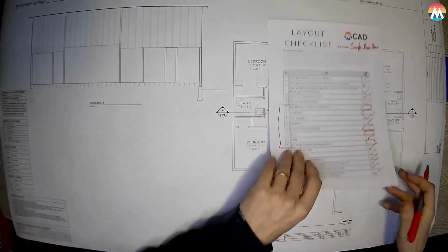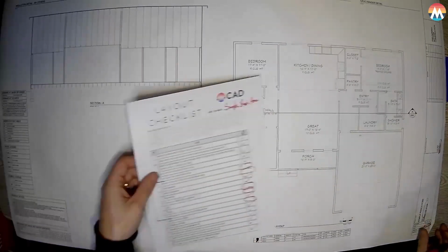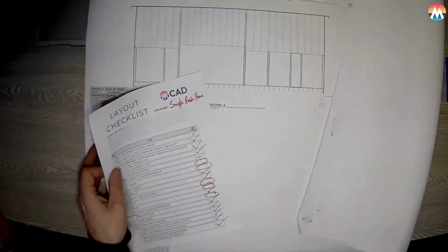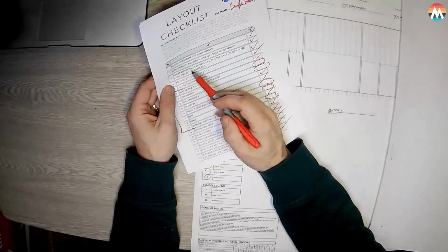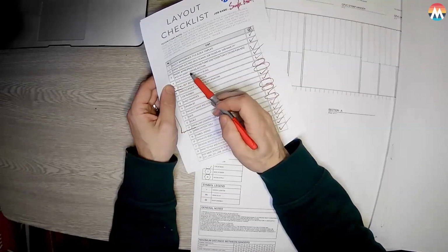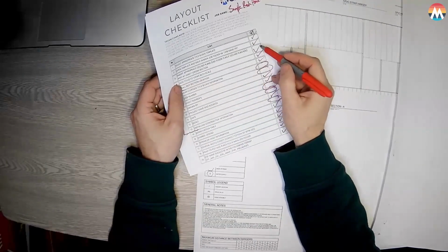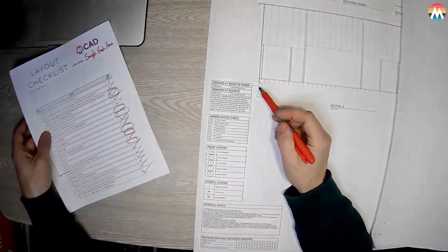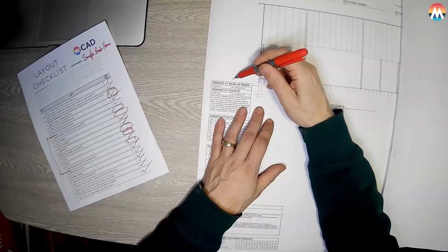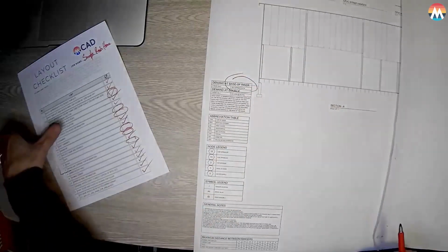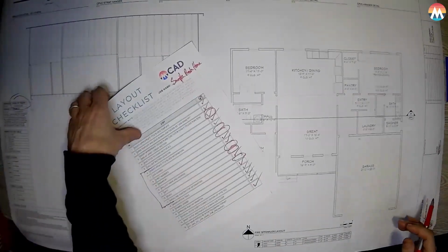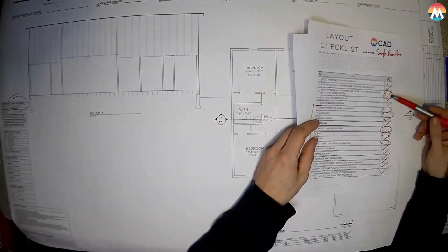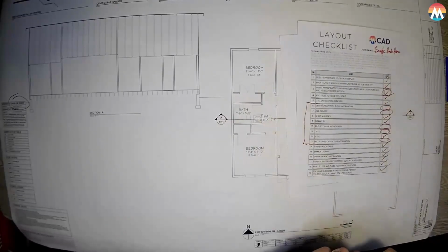Oh, there's one other thing I actually missed now that I think about it. I did this on purpose just to have an error on here, but actually I shouldn't have checked one of these off. When I have right here, insert appropriate ceiling plan and one cross section, they are inserted, but I shouldn't have checked that one off yet because this cross section needs to be moved because it's overlapping right there and we can't have that. So this just needs to be moved up a little bit to clear that. So when I get the next round of corrections back from the technician, these little things that are left are exactly what I'm going to be looking for.